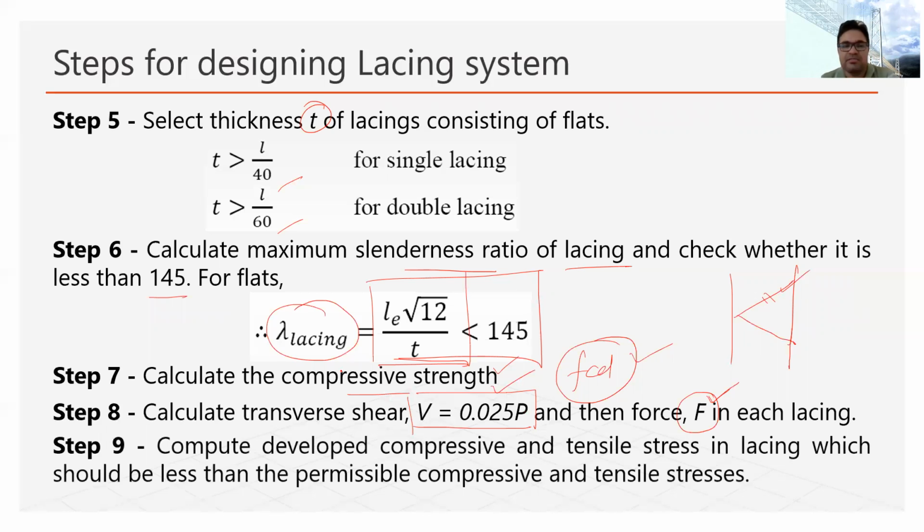Then in step 9, we will compute the compressive stresses and tensile stresses in the lacing bar, which should be less than the permissible compressive and tensile stress. We will see how we find out compressive and tensile stresses in the lacing bar and in various members. We will check that in the question when we will be solving the problem.